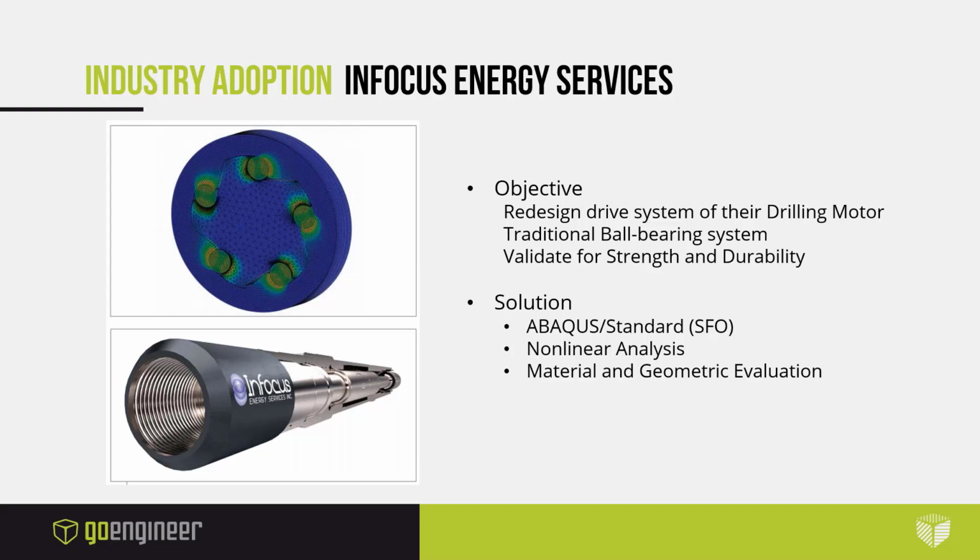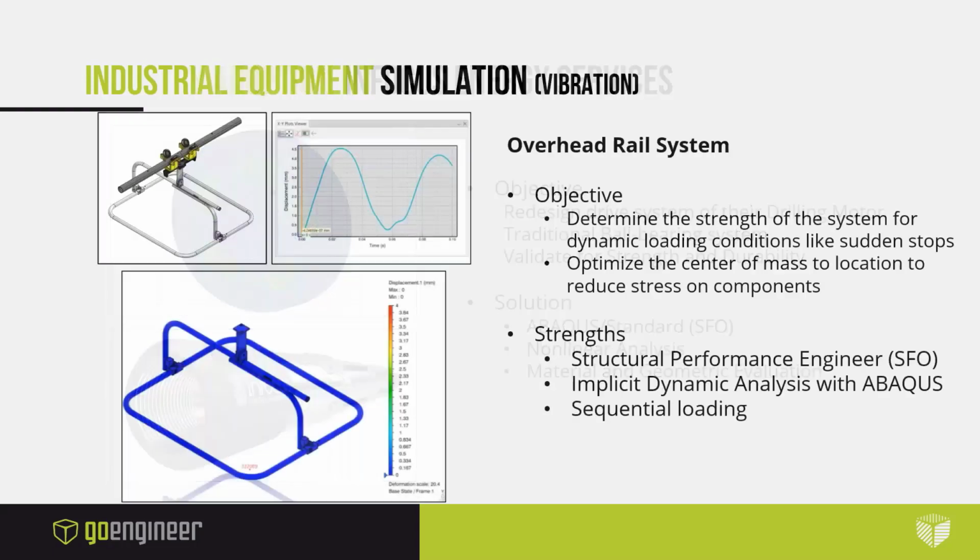And because it's such a nonlinear case, it involved multiple points of contact. It involved the rolling elements as well as the races, as illustrated by the previous slide. It required something as sophisticated as Abaqus to solve it, and they were able to use that to come up with creative designs and also create materials to execute this application to ensure it didn't fail due to the bending stresses that this little motor, or this bearing, underwent.